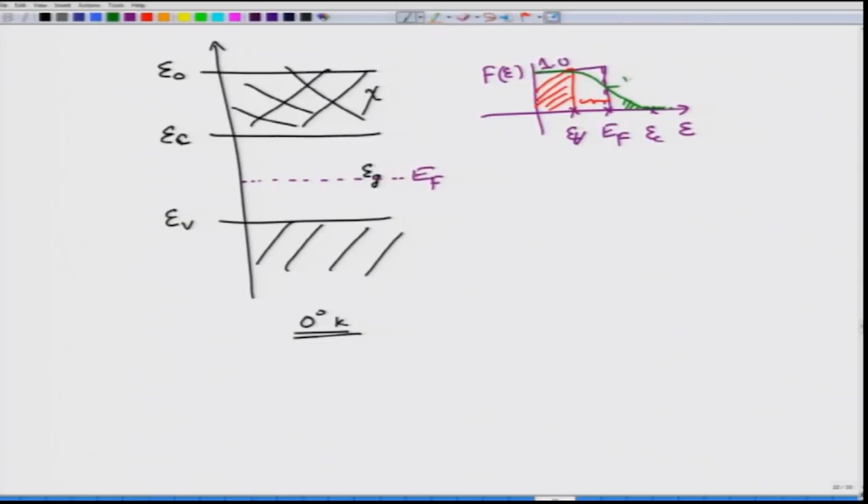Of course, at the Fermi level the probability is exactly equal to half, but again I want to tell you this is a very important concept. The Fermi level actually does not exist in a realistic sense. For the intrinsic semiconductor case, it would be right in the middle of the band gap, and of course no electron can be found in the forbidden gap, and therefore the Fermi level is a nice abstraction.